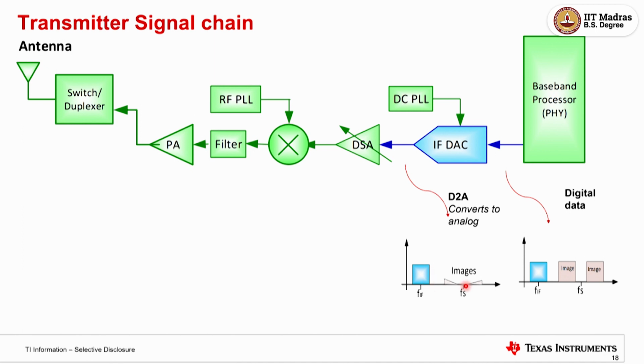So the larger and larger you make Fs, the better you will cut that. It's closer to this, so this protruding portion will be far away from your desired information. That's the importance of running this at higher and higher frequencies. If we can see that Fs moves here, this remains the same. Fs is moving farther away. So this unwanted image is at a farther location compared to your desired information, because that's what we want. We don't want it to be closer, otherwise your receiver will pick that information. So don't worry about this. We'll see what this is later.